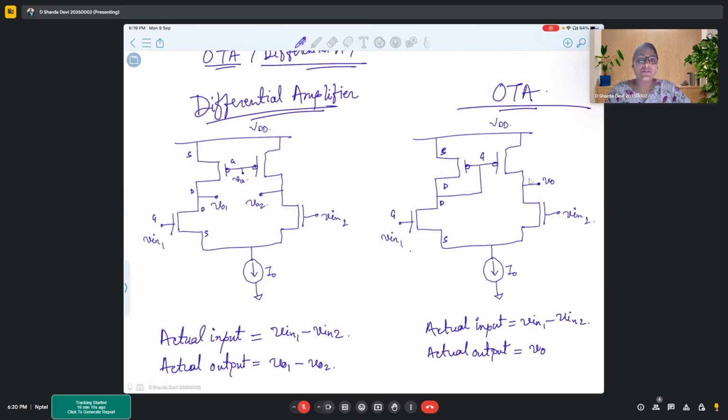But let's say there is some error which arises in the circuit itself after the input, maybe thermal error or something, because of which there is some noise in the output. Now, if the output is also differential, the circuit will provide the same amount of noise to both the output terminals. So the differential output circuit will basically eliminate that noise. So it is an even better circuit, we can say.